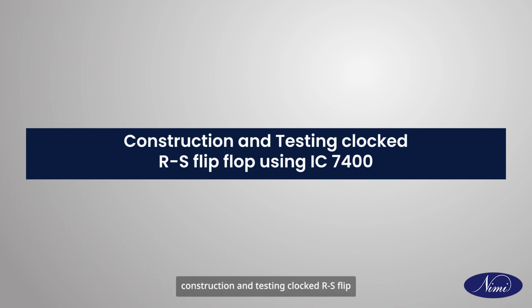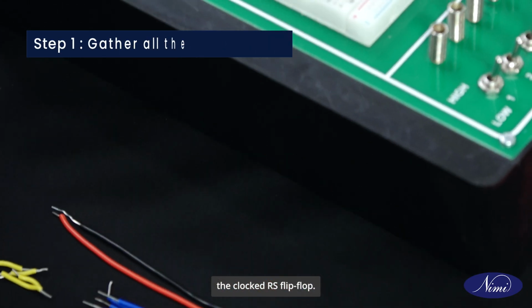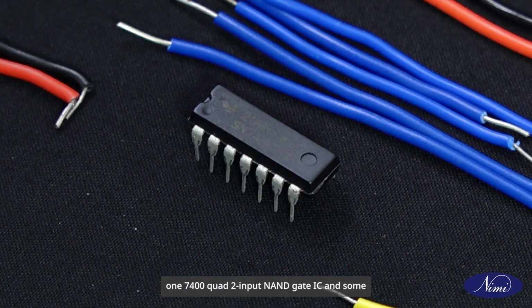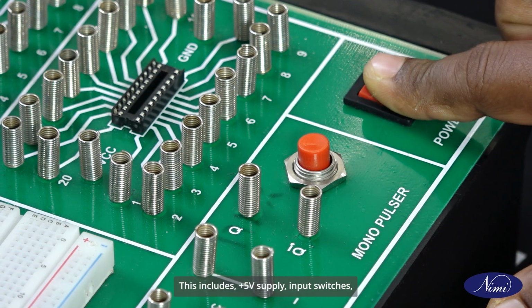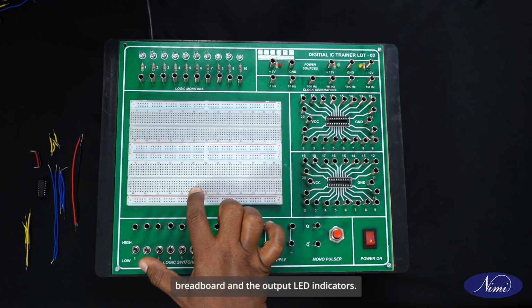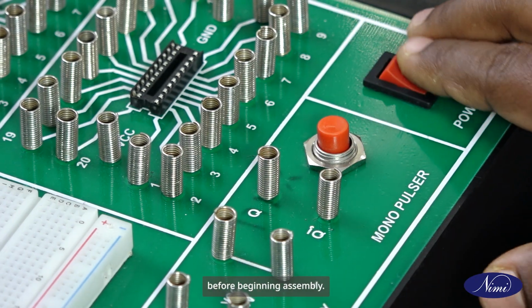Let's now look at the procedure of construction and testing a clocked RS flip-flop using IC 7400. Collect all the required components to build the clocked RS flip-flop. This includes the digital IC trainer kit, one 7400 quad 2-input NAND gate IC and some jumper wires. It is necessary to check all the required sections of the digital IC trainer to ensure its working condition. This includes the +5 volt power supply, input switches, breadboard, and the output LED indicators. Make sure to thoroughly inspect each part and verify you have the full set before beginning assembly.